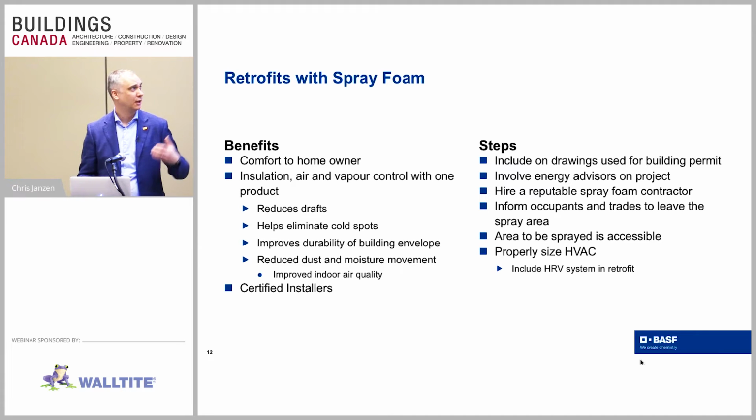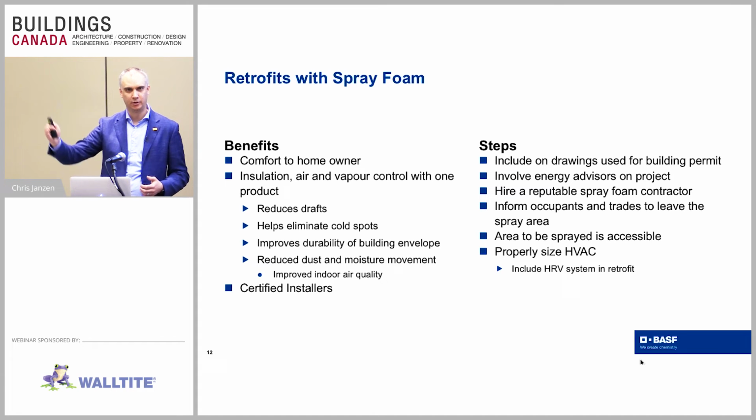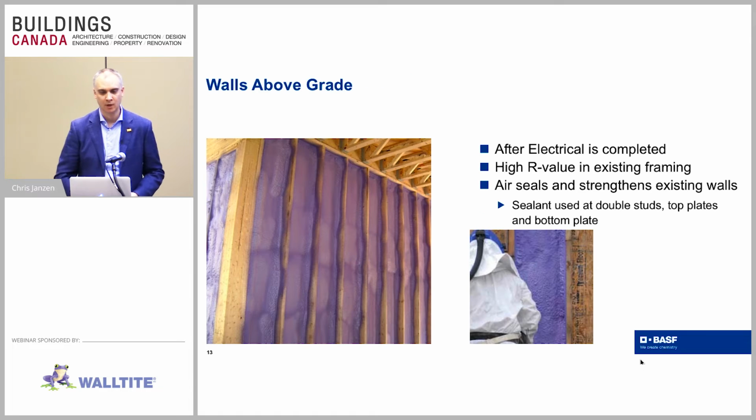And you want to make sure that that area is accessible. As a general contractor, you don't want to have drywall all the way up to the wall. They need about a 3 to 4 feet area to move around the walls. If they're working on the ceilings, they're going to have to be able to get their scaffolding in there, so you need clear floors. So again, based on retrofit applications, that can be challenging at times, but it's just one of those key little things to keep in mind.